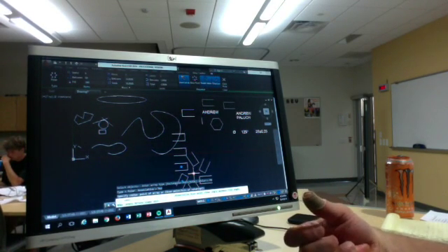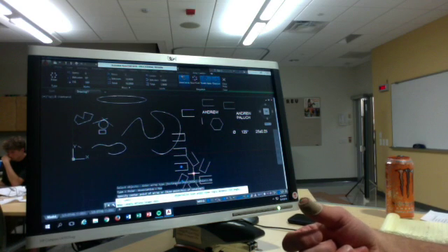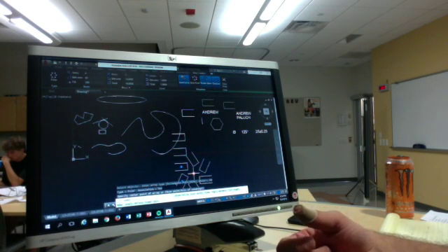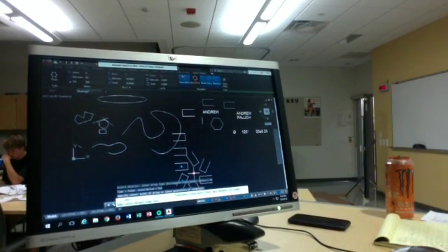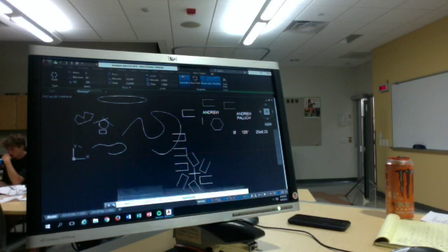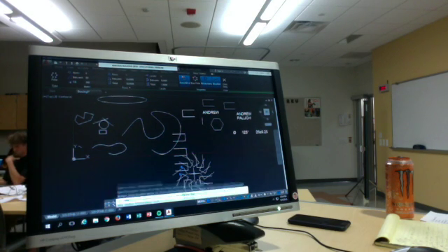So where is that at? Rotating. Associative base point. Yeah, so let's say you need 12 instead of 6, you type in I. You enter the new value for the number of items that's actually going to be in it. I want 12, so I hit 12.